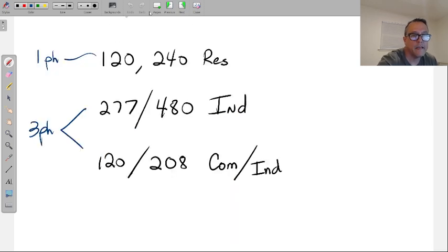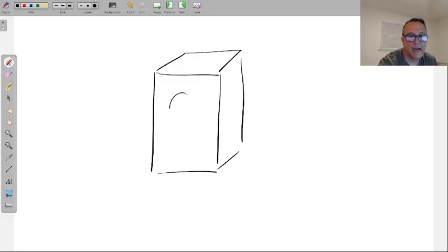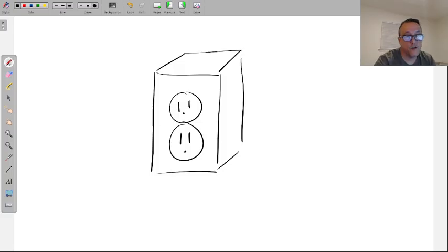But for example, if you had that box, right, you have your watertight box here, and you had an outlet here, and you put this outside, sure, the rain's not getting into the box because the box is watertight, but the outlet is getting all that water all over it. So it could, in a sense, not always, I've seen these things get rained on all day, but you'd be surprised. But it could, in a sense, as it says there, interfere with the successful operation of whatever you have plugged into this.